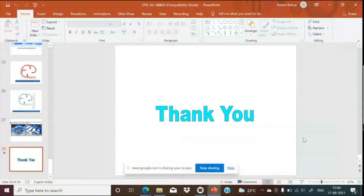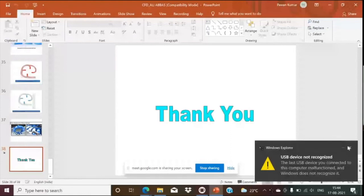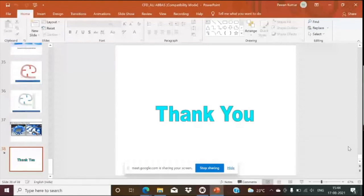Actually, for doing this, we have to do a grid independence test, where we make 2-3 different meshes, coarse, dense, and very fine, and then we do the simulations and see how the output parameter is sensitive to the mesh density.